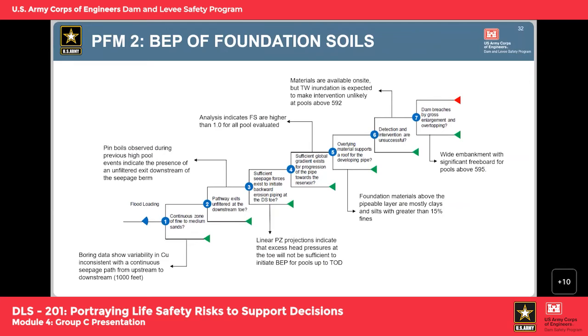For intervention with the BEP failure mode, the dam is under 24-hour surveillance when the pool is above 585, which is approximately 10 feet, 15 feet below top of active storage. And the project personnel do initiate monitoring activities if boils are observed.